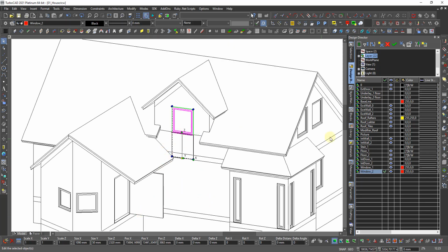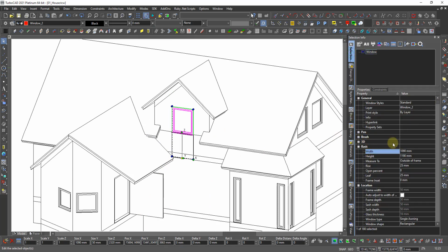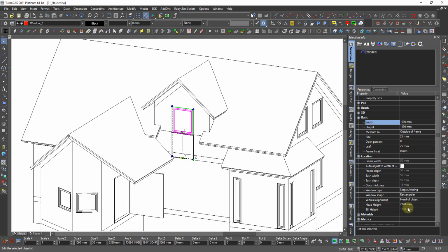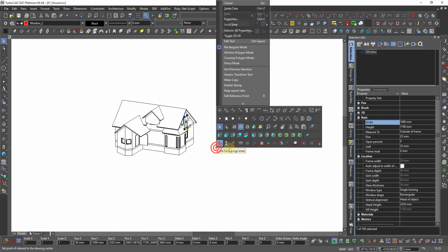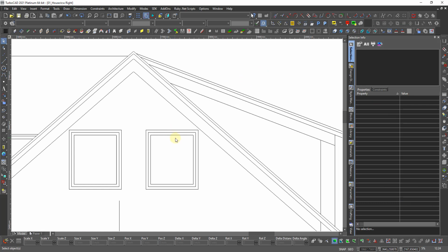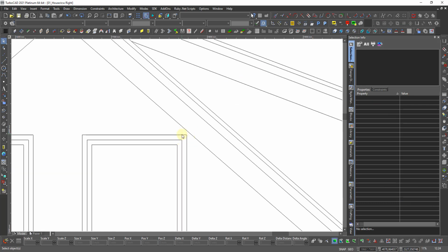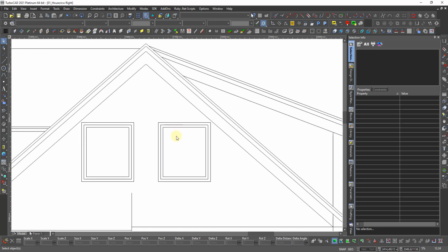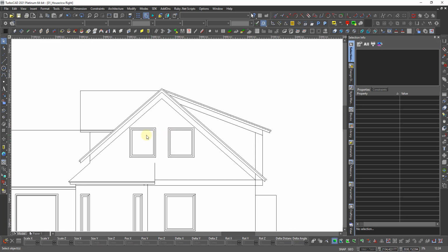This window, I can go selection info and I can see where it's telling it's 1130. So that can be lower if we want. This window, 2320 by 1130 still. If I see it from the right, this little bit small, because I think from here we should come 43mm down with the ceiling, and the picture doesn't say that. It doesn't show like that. So I think this window is standing on 2 meters.